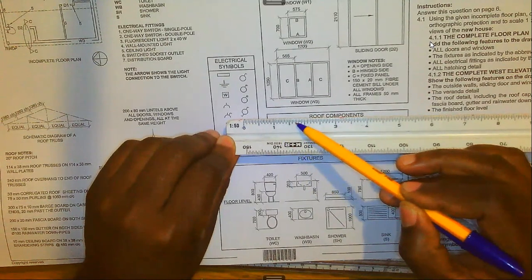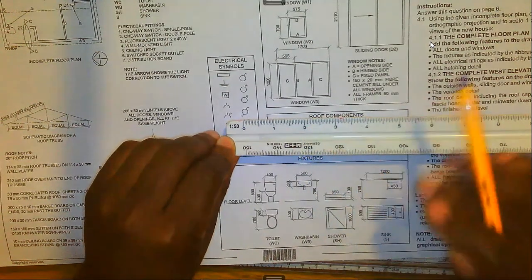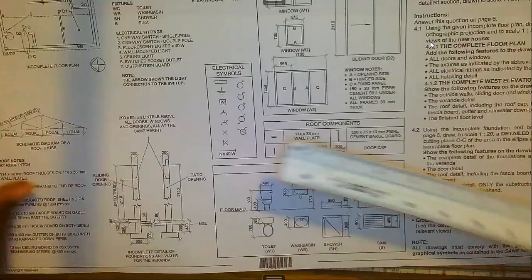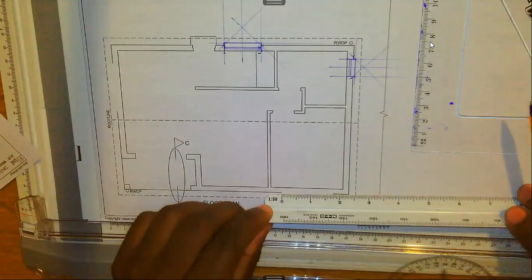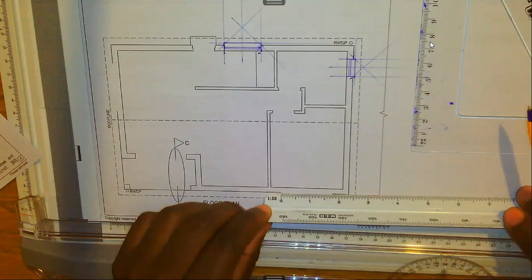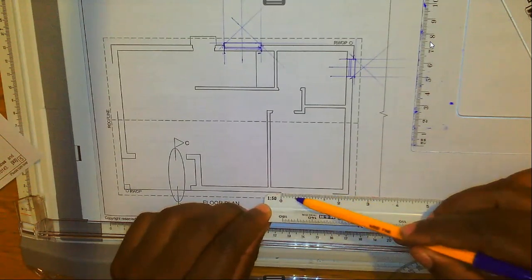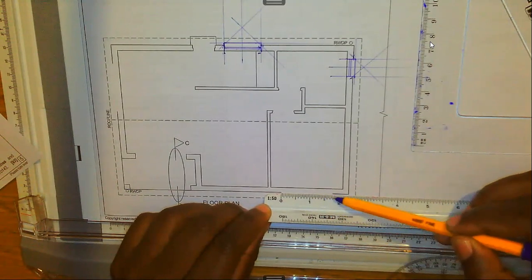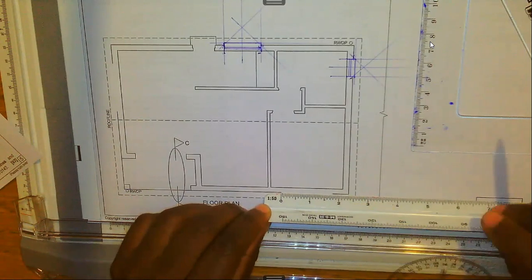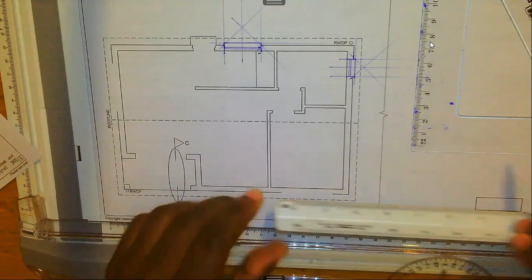This is straightforward. Then I can easily check there, right? Whether this is 1,700, you can see that it's overlapping slightly. That's 500, 1 meter, 1.5, 1.6, 1.7, 1.8. So it's over by 100 millimeters. So I need to reduce that space.